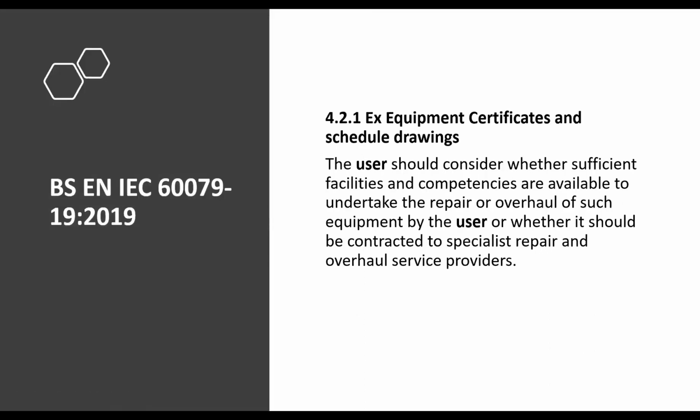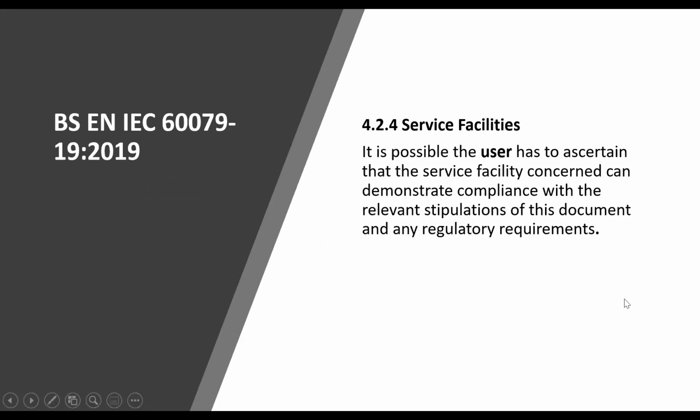Again, another quote from the standard: the user should consider whether sufficient facilities and competencies are available to undertake the repair or overhaul by themselves, or whether it should be contracted out to a specialist repairer and overhaul service provider. But if they do that, the user has to ascertain that the service facility concerned can demonstrate compliance with the relevant stipulations of this document, which is the International Repair Standard for EX equipment.